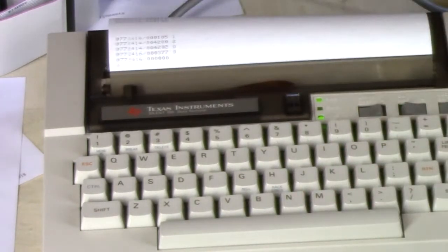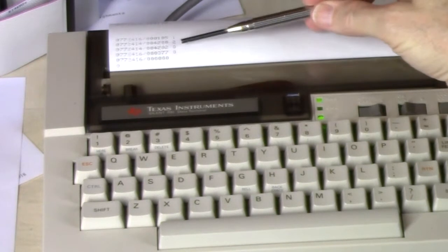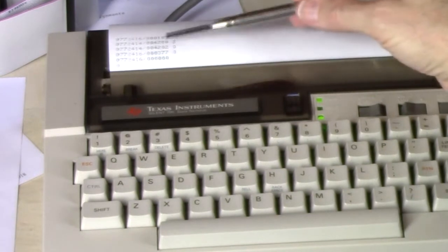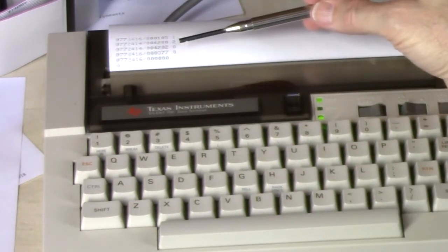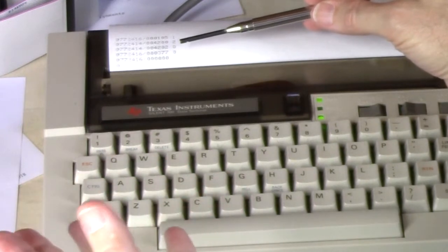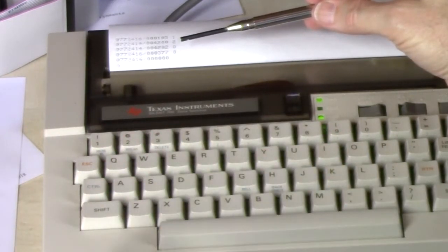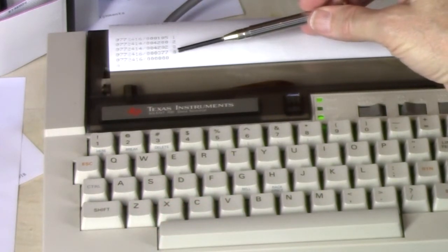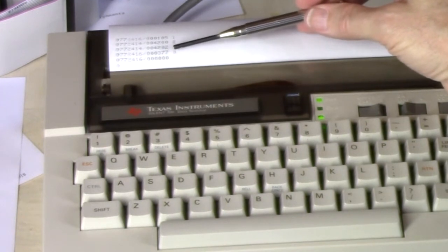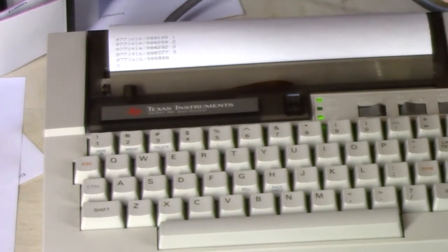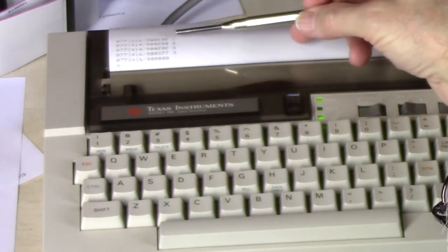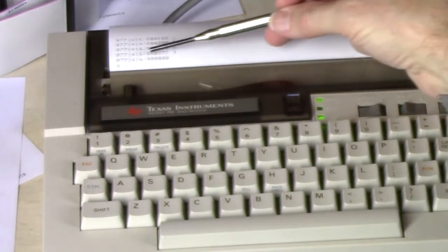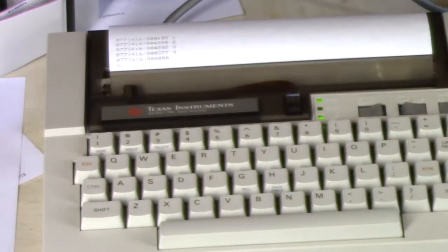that we're obviously accessing different memory here. Anytime we access the data, we're reading whatever address is currently specified; that address's data is presented on the bus. So we read that. It's the 377, which is an FF, an unprogrammed cell, and that was at location 1, because that was the last thing we put into that data buffer register. Well, when I set it back to 0, now we're reading location 0, and you can see that that is indeed 0.